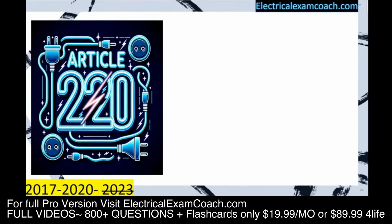This is lesson 2.2 in our video series, and we're going to be diving into Article 220 load calculations. And just to clarify what we're doing, we are calculating the demand on a home in order to be able to size the main breaker, the wire, the pipe, the service, and everything that goes along with it. But before we can size all that, we have to know what is the demand on this home. And that's what we're going to be learning over the next few video lessons.